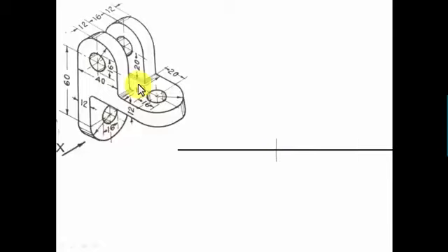Let's go ahead and find the maximum width as well as the maximum height of this entire object, so that I can make a box into which I would be inscribing the front view. This portion over here should work out as 20. Let me show you why. From this point to this point, the distance is 40. From here to here, it should work out as 20. Since this portion is the radius of the semicircle, this distance is also going to work out as 20. So 20 plus 20 is 40, and this is 40, so 40 plus 40 overall should work out as 80 millimeters.